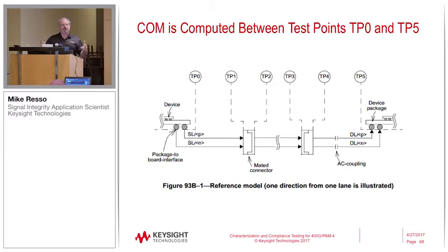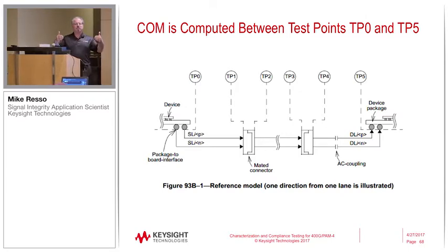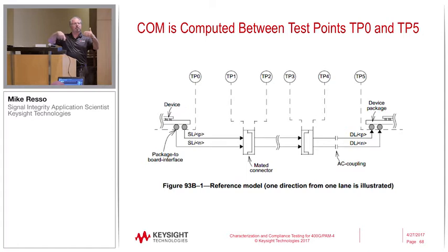So of course, when you have a full 4-port measurement or full 12-port measurement, the machine, the VNA or the TDR, automatically sequences the input stimulus, reading the output on all other 11 ports, then switching the stimulus automatically, and then reading the other 11, and just rotating that way, and that's how it gives you a 12-port S parameter. So how many cells in a 12-port S parameter matrix?